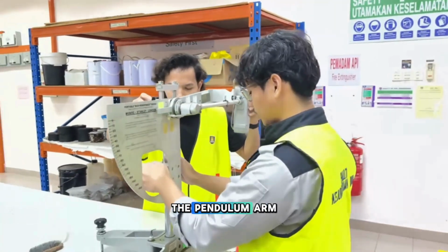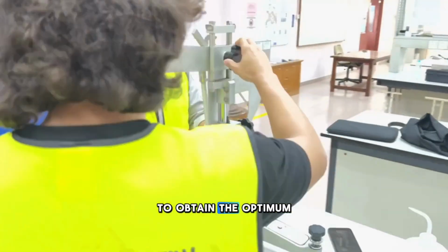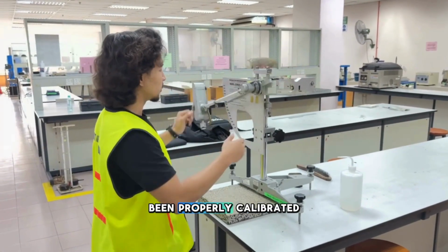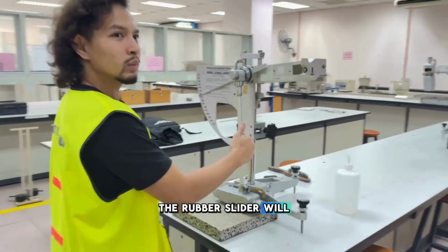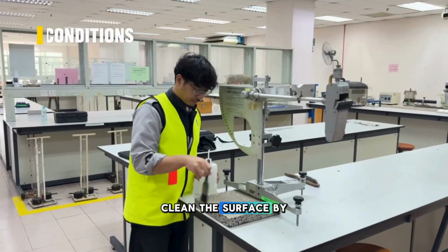Adjust the height of the pendulum arm by turning the lifting screw and the knob behind the scale to obtain the optimum position. This is the condition after the apparatus has been properly calibrated. The rubber slider will make contact with the surface when the pendulum arm swings. Clean the surface by using the brush.